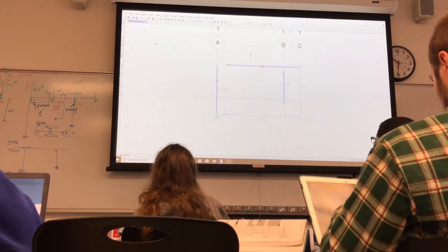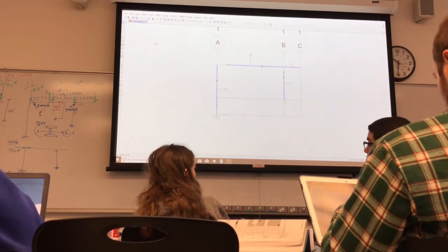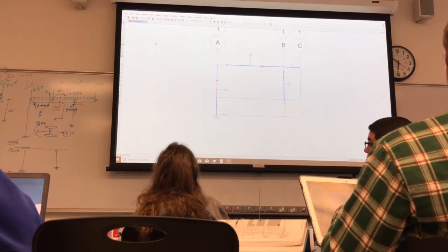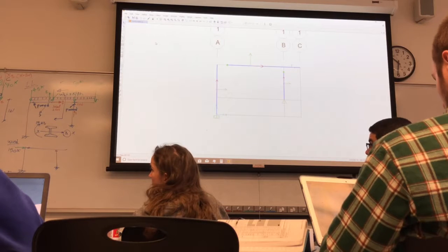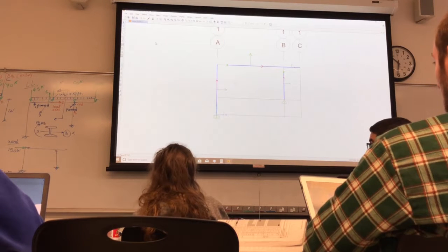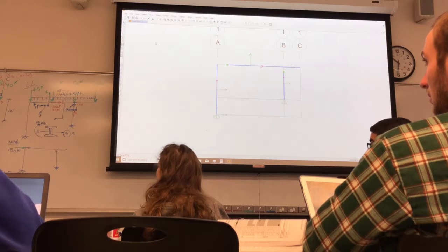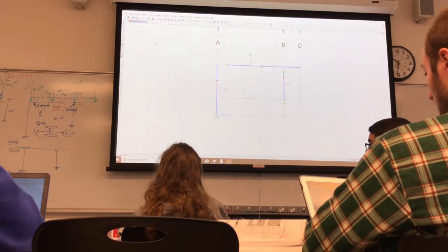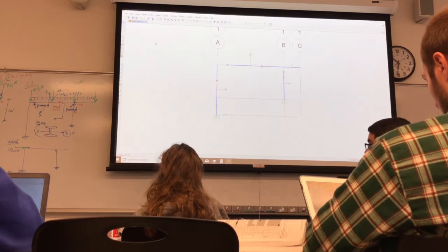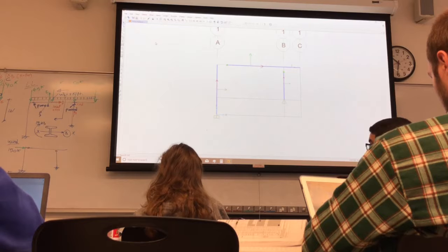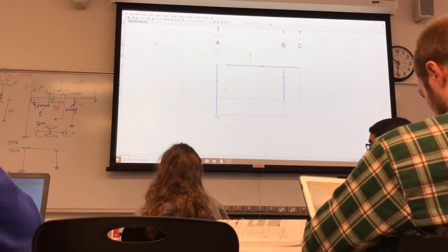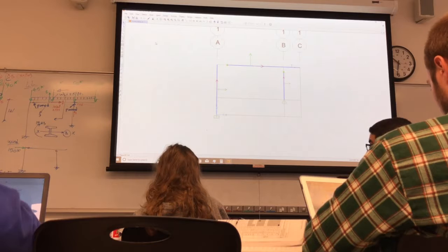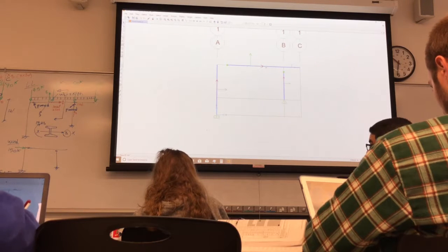Any other questions? If the connection on the left between the top beam and that first column wasn't a shear connection, say the top beam laid on top and was pinned in the same way, would you just pin that other one? Then I would pin the column, the same way. That's why in steel design we have to show where the pin is. You don't just put it anywhere, because it depends on how you connect it. So that's how it looks, and now we need to apply loads.